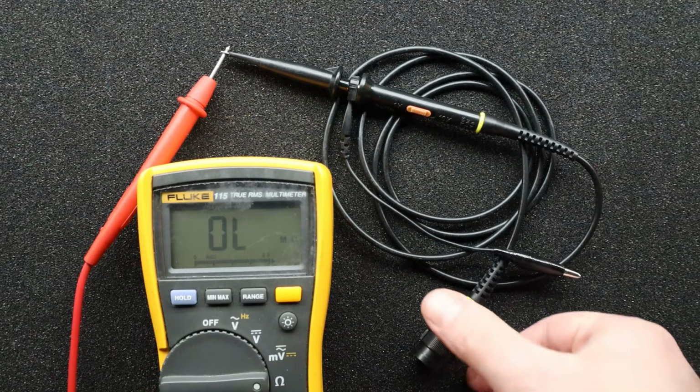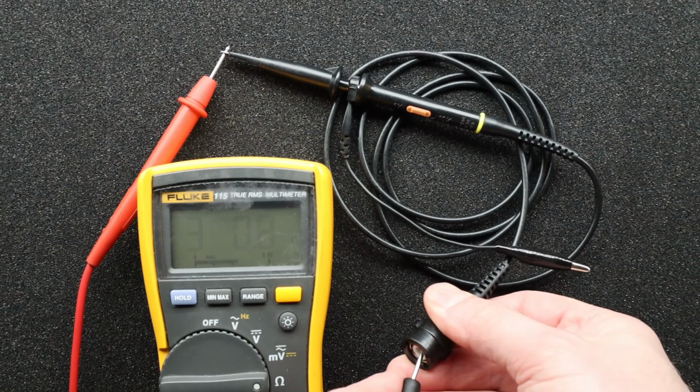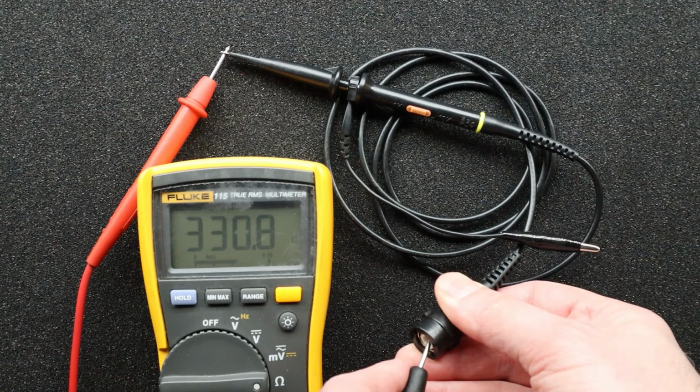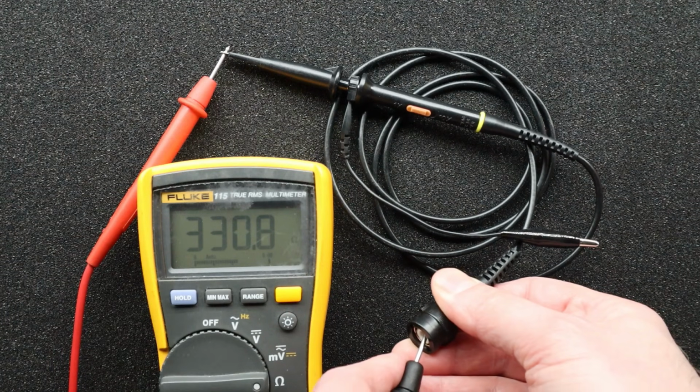But is the resistance really 0 in ×1 mode? No, there is usually some amount of resistance. In this case, it is much higher than the 75 ohms we need. Besides, even if there was 0 ohms, we still wouldn't want to use a ×1 probe. The characteristic impedance of the probe cable is wrong, and it isn't designed to carry current. Remember, the load is now in the scope, so the current would travel through the probe cable, although it's not very much. So, what do I suggest?